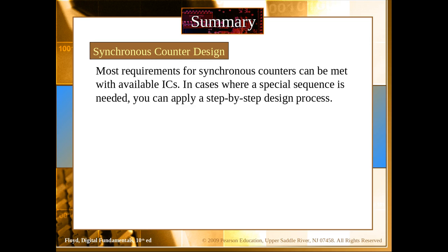Let's talk about some counter designs. We would need to design a counter, especially if the sequence is not the regular binary sequence that we normally use. We can design a counter of any sequence with any order. For example, we could design a counter where the sequence is not in binary terms but in gray code terms. After 00, the next number is 01, but the next number is then 11 and not 10.